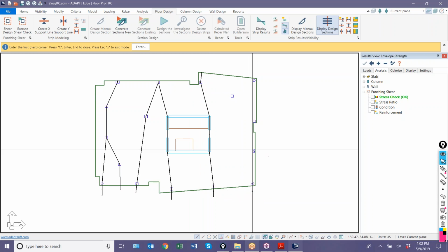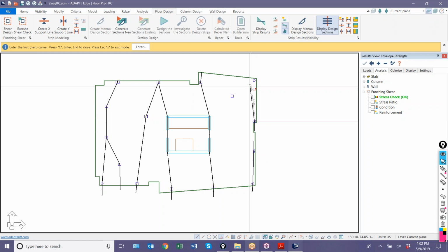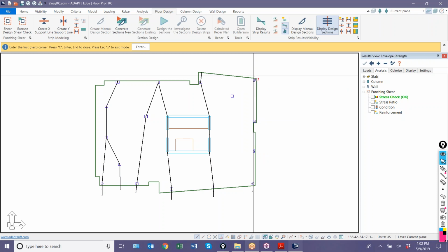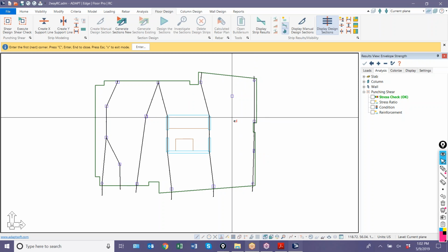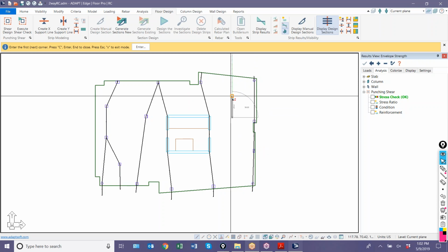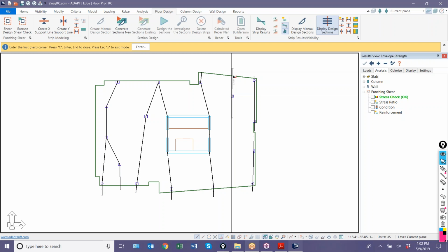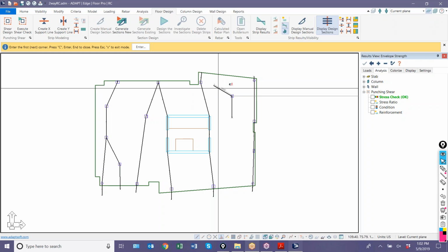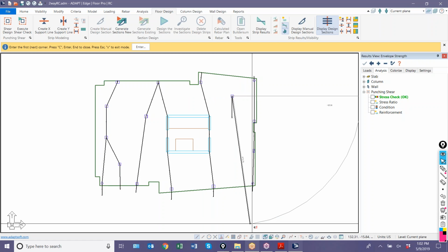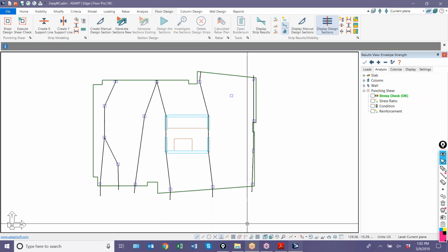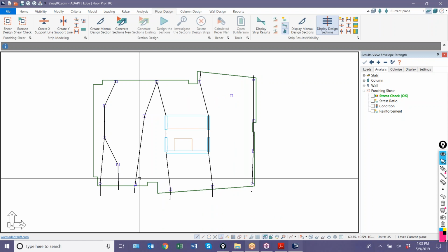This one I'm actually just going to take through the notch here and something like so, and then here I'm just going to create another strip along that path. Or I could just allow the program to generate a middle strip between these two, which would be along that path anyway. So that might be an easier option there.